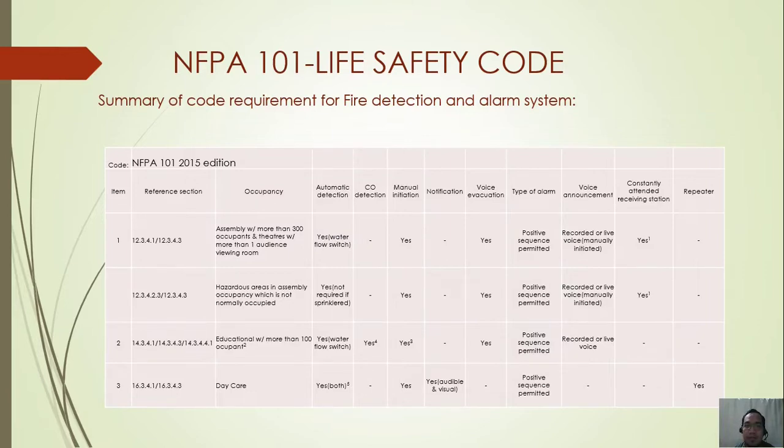Let's say if there's a fire started from the busted sprinkler, there's a delay of 15 seconds for the operator to check the control panel where this fire is originated. Otherwise, if it's not acknowledged within 15 seconds, then a general alarm will be triggered in the whole building.